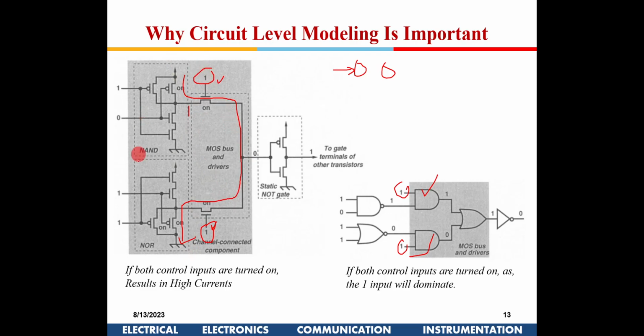These kinds of issues can only be detected this way, because this could be a stuck-at-1 fault, where I'm doing a fault simulation. While fabricating, this can happen. That is the reason why, when we do logic simulation, although we say only one of them should be 1, we also take the condition that if both of them are 1, is the circuit safe for operation?